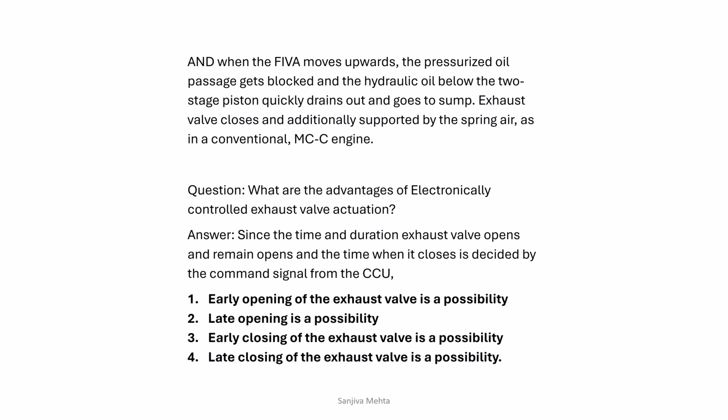As things stand today, early opening of the valve is not possible and cannot be carried out in the engine. Although, if you want this, you can amend the software and make it possible, the engine maker has not made it possible, so it is not available. Late opening is a possibility and is available. Early closing of the exhaust valve is a possibility and is available. Late closing of the exhaust valve is a possibility and is available.